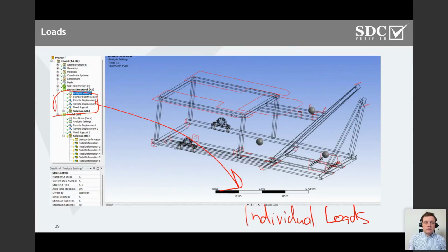And this is perfectly okay to run the analysis already. So you have a gravity and you want to check if your structure is safe enough under just standard Earth gravity, no extra loading. It is possible to run this. You have maybe from other department output file where you have all of the necessary loads combined. You know which condition is critical and you only want to check that one. It's perfect for you and you can run this. So at this step, we just read your loads and allow you to modify your loads.